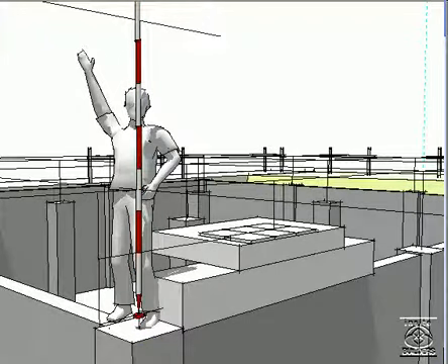So let me run through those numbers again. Say this tip of the story pole is the same elevation as the working reference point at the corner of the property at 34 feet. And the top of the finished tile, according to the design drawings, is supposed to be 35 feet 6 inches. That means the distance from the transferred reference point elevation to the top of the tile is 18 inches.